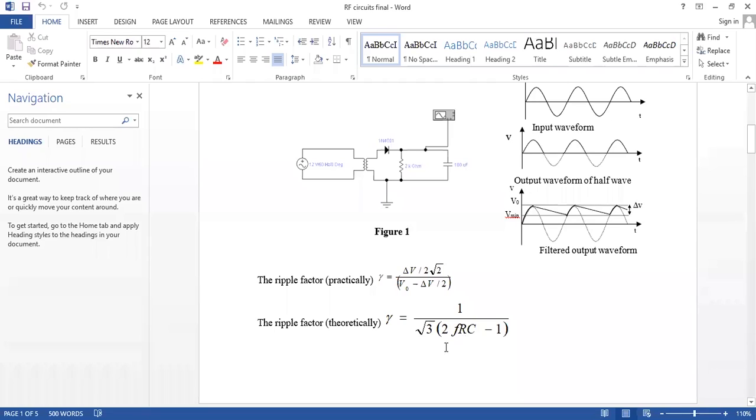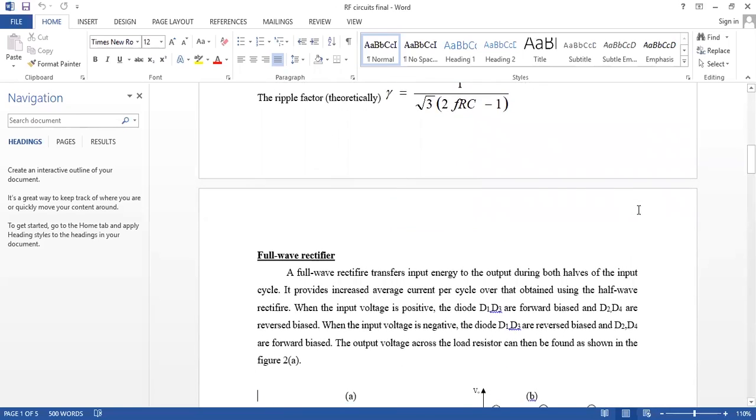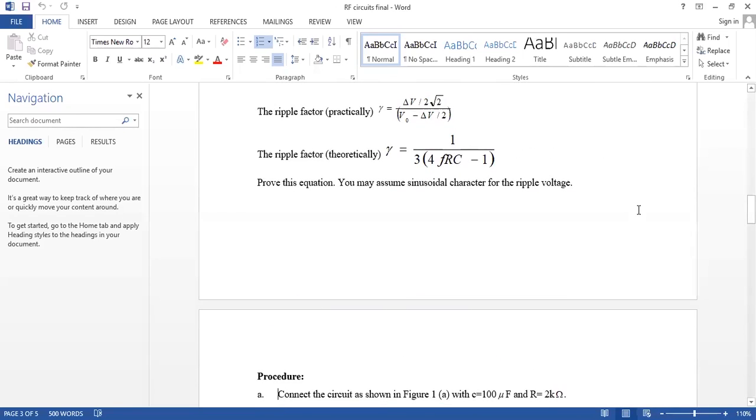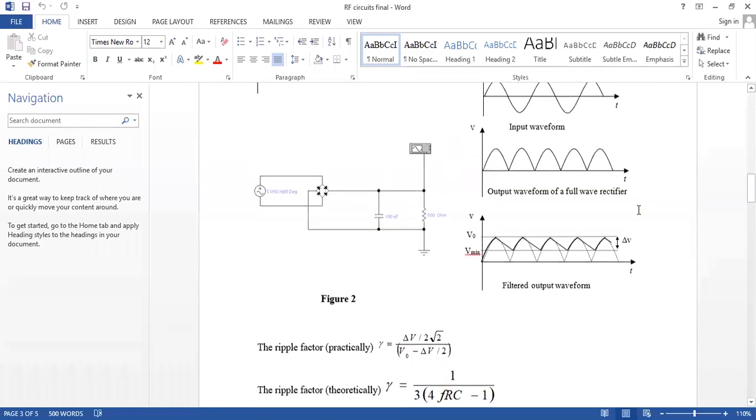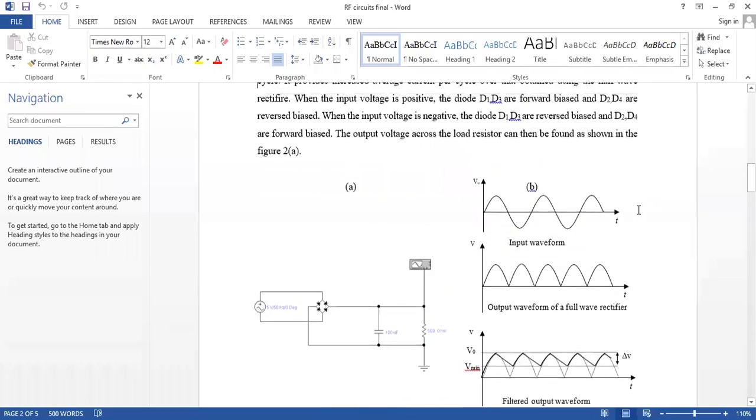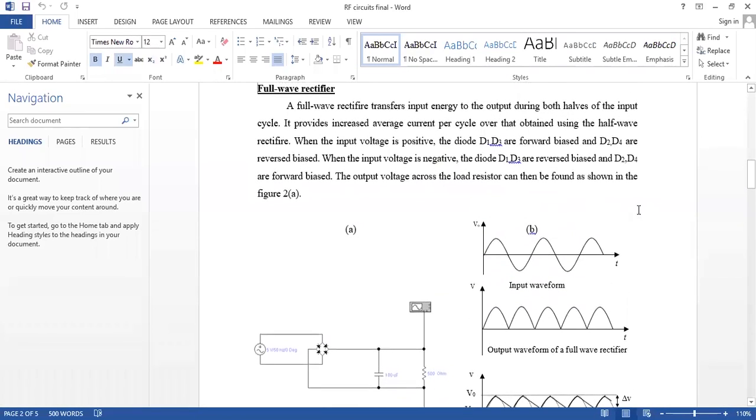Okay, before that, this one is the full wave rectifier. Okay, the full wave rectifier also has two circuits. This one and another one. Okay, you already studied this in A level. The current will flow in this direction. When current flows, this one is positive and this one is negative. Okay, we will use this diode for the first half cycle, so the positive one.